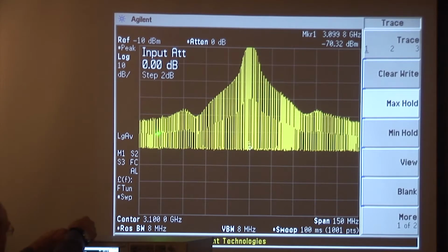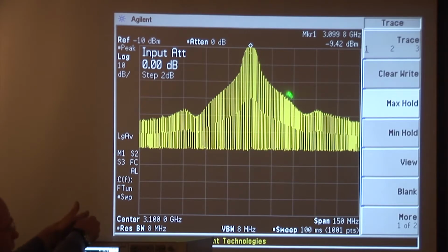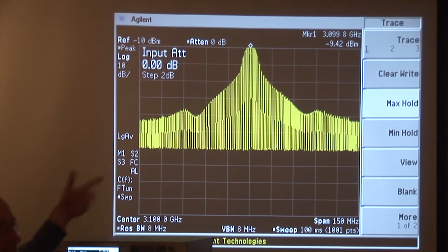But you see that you can't do it if you're just sweeping across. If you're simply sweeping across, there's no way to selectively or interactively change noise figure and attenuation as you're going across through the spectrum here. So now I've covered two of the problems. The probability of intercept, which we see is still low. I mean, we still don't have a good fill-in on any part of the spectrum right now, although we are getting a good outline for what we think it might look like.